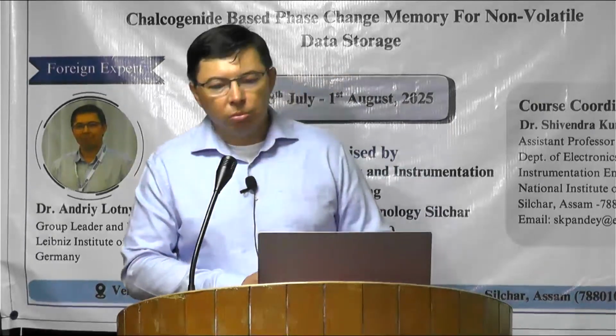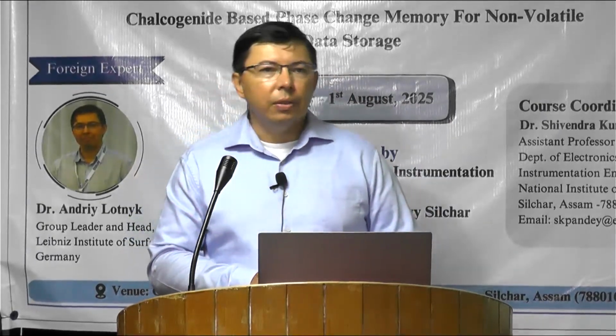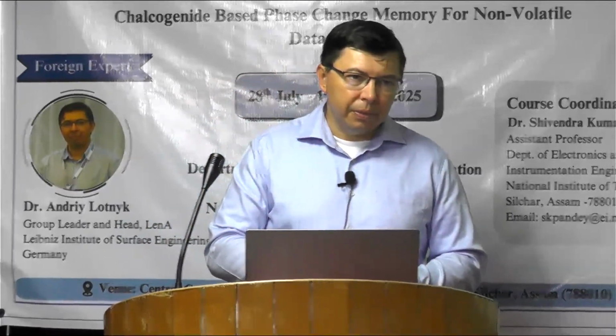Professor, what we saw is that from crystalline to amorphous is logic 0, and changing from amorphous to crystalline is logic 1. Does it go into a metastable state at some point? Yes, it's also possible. It's called multi-level capability, MLC. You can achieve it if you apply sequential pulses, for example, to the crystalline phase.